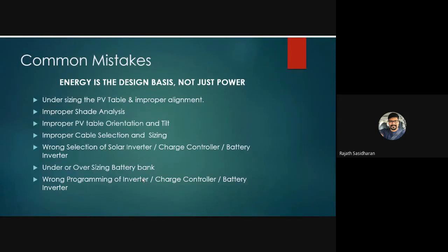You can do this math. It's very simple. It's not rocket science. Ideally, in case you wish to go for a solar photovoltaic plant, always remember this energy. What are the units of electricity you are consuming every day? Undersizing the PV table and improper alignment. In case you are in the northern hemisphere and you face the panels north, it's of no use because the panel is shaded by itself. So it will not produce any energy.